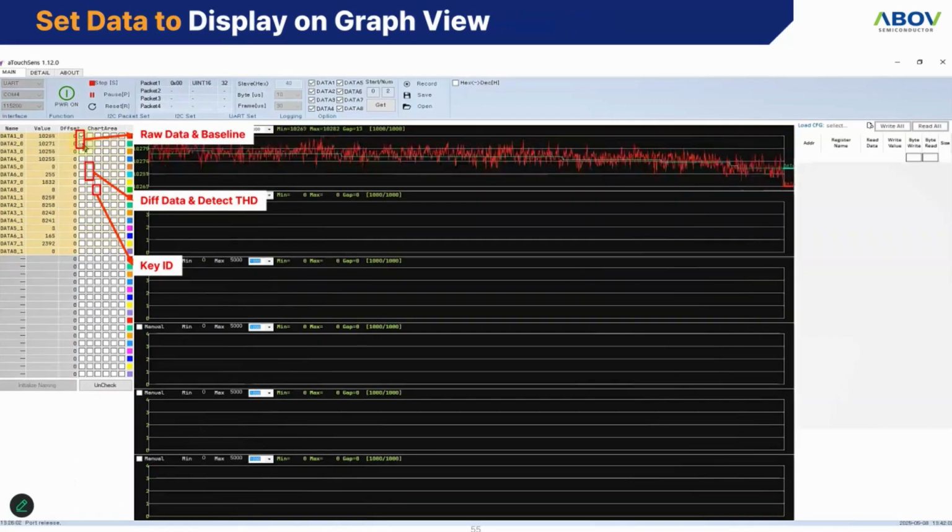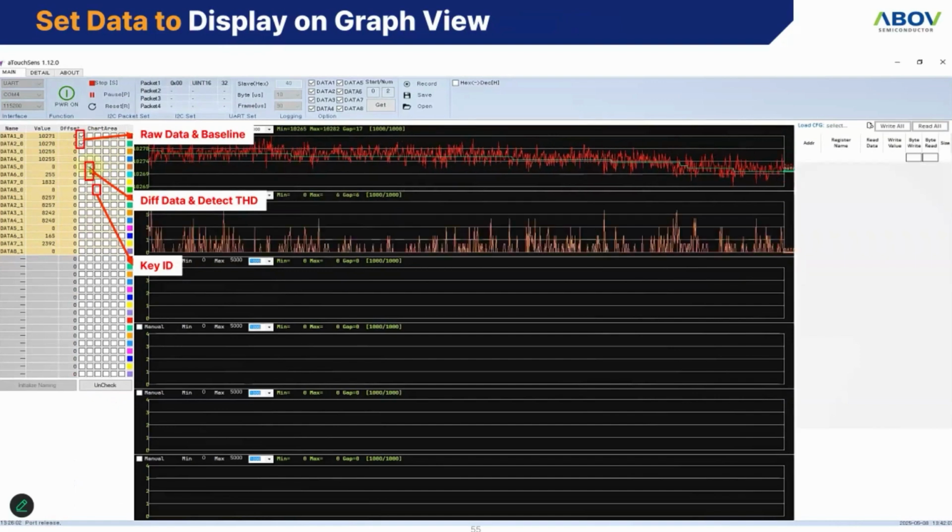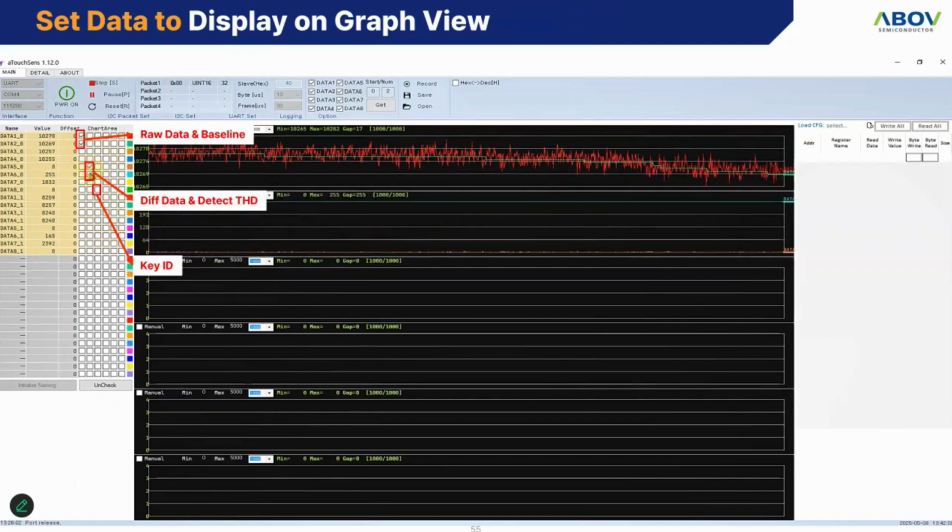As talked about earlier, our touch MCU uses two sensing frequencies. One channel has frequency A and frequency B. We are getting raw data for two frequencies per sensing, and we are also calculating two baselines. In normal conditions, the two frequencies from each channel are almost similar. So in this scenario, we can just test it with one frequency, which is frequency A.